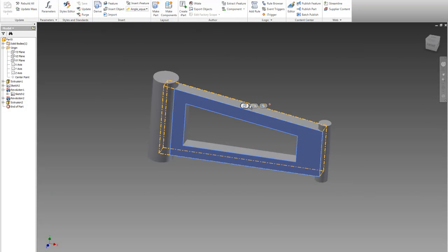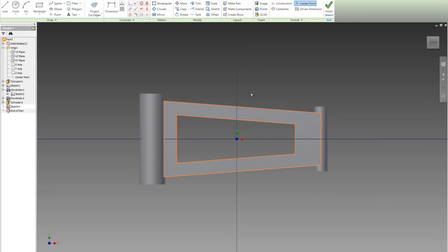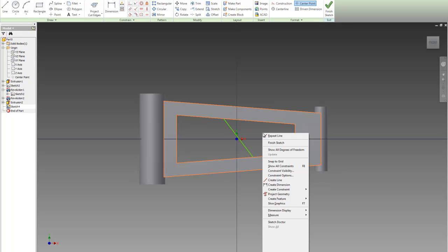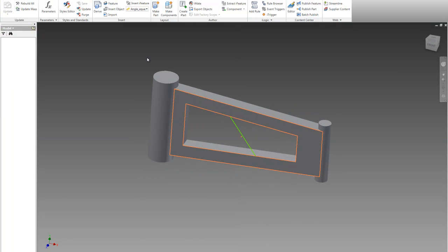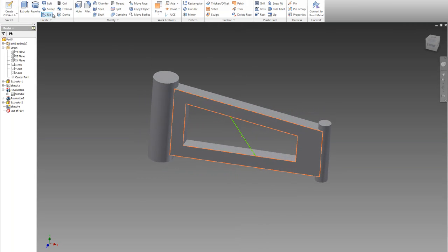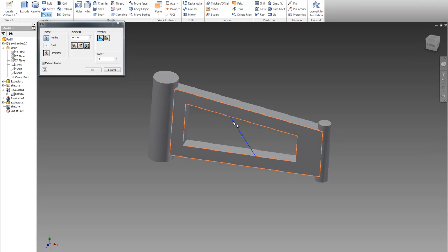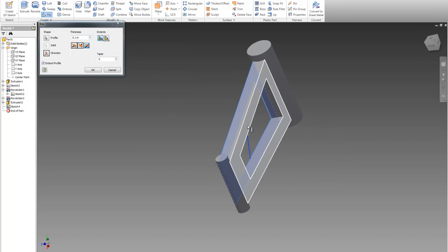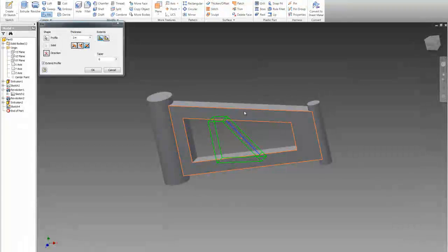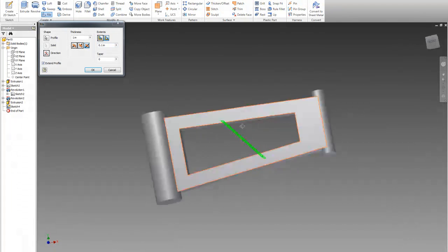As you're going through your design process, it's good practice, if you know you're going to be doing something like iLogic tools, where you'd want to change the length or the height, to go in and type in words, because then you know what those dimensions are when you're going to try to reuse them later. Continuing on this design, I'm just going to finish off here with a rib. Nothing new, but just good practice here of reusing dimensions that are available to me in the model.